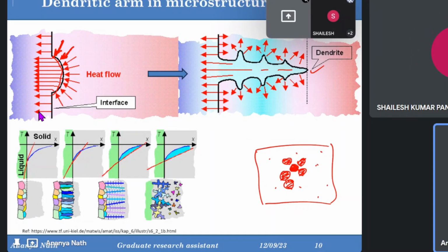So rather than just mugging up the things, you just tell me what do you think by the stable grains? Yes, I am telling about the stable grains. If delta Gv will become more, R star will be less. That means delta G star will be less. If delta G star is less, the nucleus can be stable at lower size.